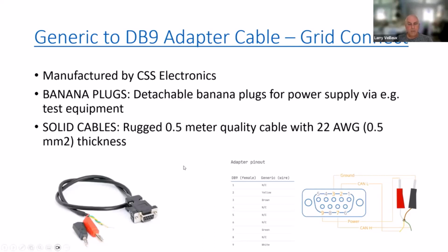In this case, that's true even for that CAN logger that we got, it doesn't have its own power supply. So in this case, we can grab the power off however you're powering everything else in your system, to provide power to the CAN logger. And then this would plug into the CAN logger. And these are the twisted pair of wires that would plug into the CAN bus on your CAN HAT unit. And again, I'll show you that in a moment.